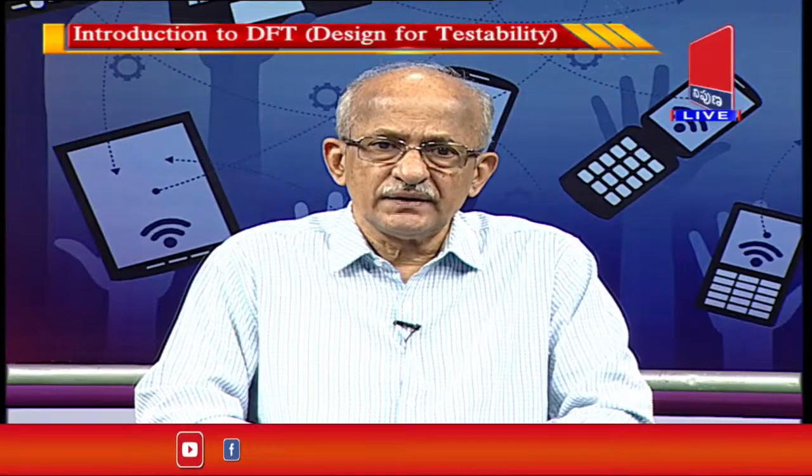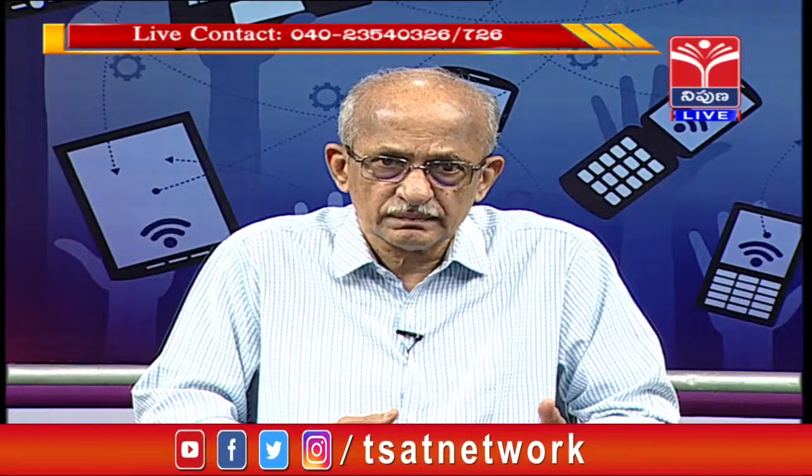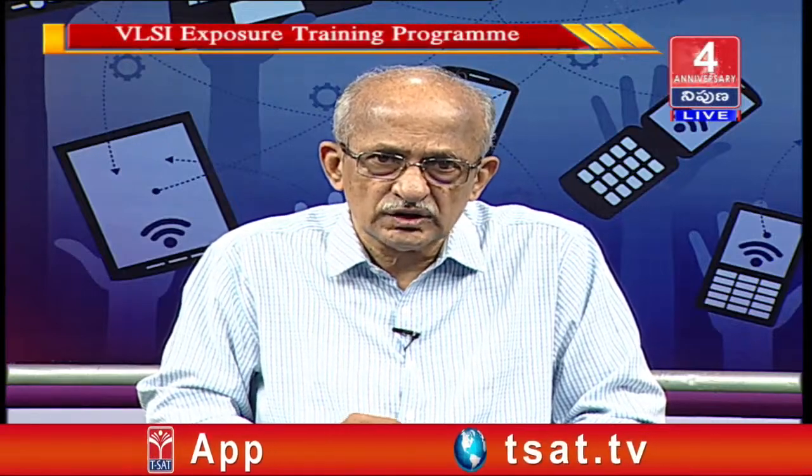The chip then has got two modes of operation. One is a test mode and the other is a functional mode. So when the chip is getting tested, it is put in the test mode. Once it is in the test mode, it gets tested and then it comes out. Comes out means comes out of the tester, not that it is put in the tester. Tester is not like an oven or a furnace where you put the chip inside. Okay. The chip is tested, and when testing is done, then the whole wafer will be diced by what is known as laser dicing, and it will be cut into different ICs, and the different ICs will then go for packaging. Only the good ones will go for packaging, the bad ones will not go for packaging.